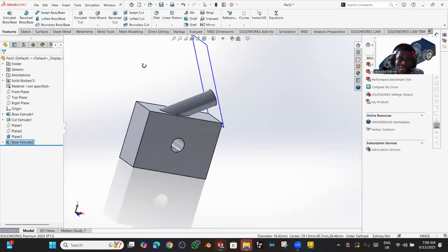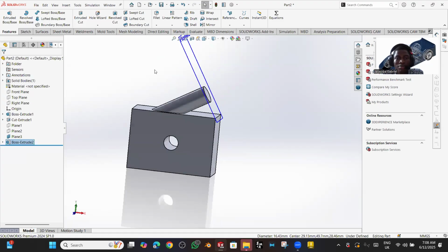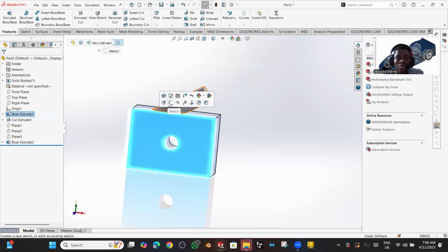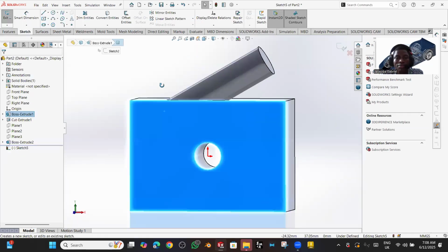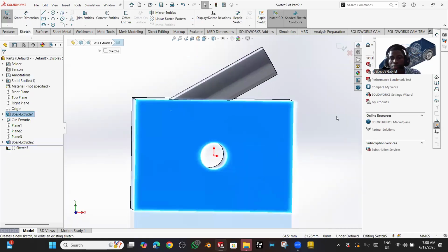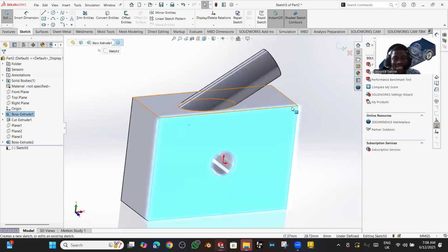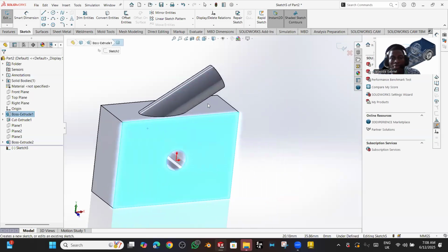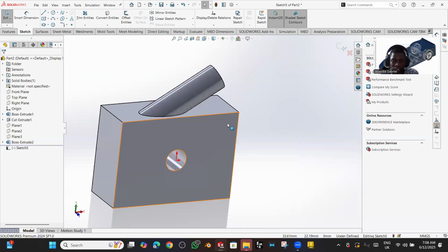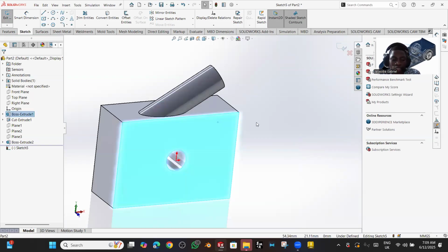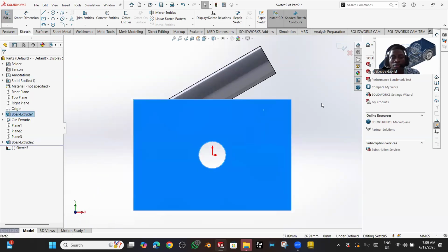Now, cut. I want to draw. Let me hide this first. So I want to create a new sketch, right? If I have my sketch like this, like I am editing, if I have my model already rotated, and I want to make this face normal to my view, what do I do? I'll select this face and I'll press Ctrl 8. Now it gives me a normal view.